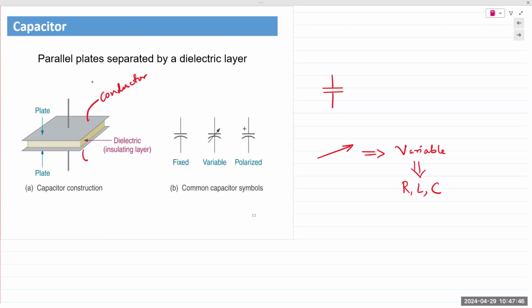That gel-like film acts like an insulating material, but it needs to be activated by a voltage applied in a specific polarity. And hence, these capacitors, known as electrolytic capacitors, do have polarity, just because it needs that voltage to activate that gel in a specific manner. For all other capacitors, you can connect them in a circuit without any polarity.